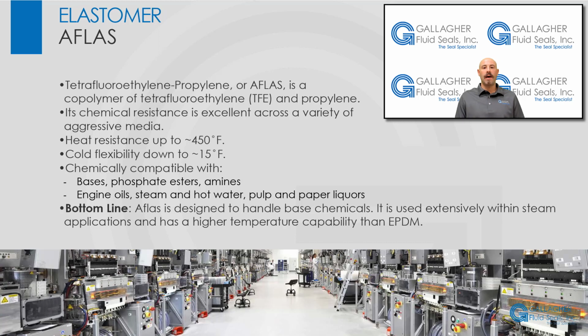AFLAS is chemically compatible with the following: bases, phosphate esters, amines, engine oils, steam and hot water, and pulp and paper liquors. AFLAS is not compatible with the following: aromatic fuels, ketones, and chlorinated hydrocarbons.